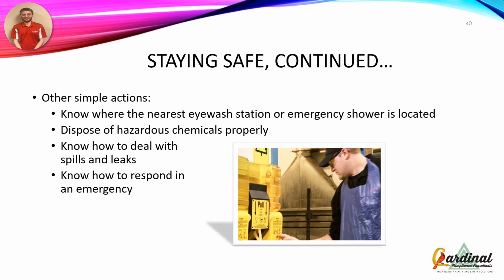Also, other simple actions: know where the nearest eye wash station and emergency shower are located. They should be right near any caustic material that you might have. Dispose of hazardous chemicals properly via local regulations as well as state or national regulations. Make sure you're disposing of those the way you need to be. You're not just throwing acid down the drain, so to speak.